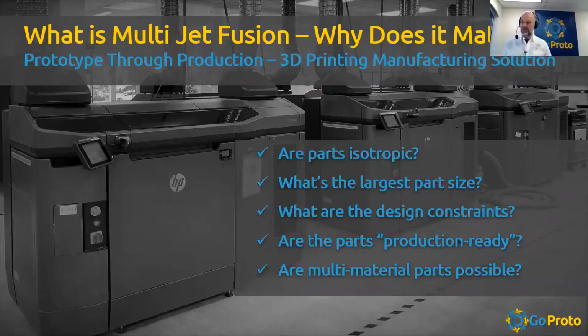What are the design constraints? Again, these are questions, as Kristen mentioned earlier, that some of you had as you registered. So these are directly from the market. Design constraints, that's an exciting thing about 3D printing. Why 3D printing is interesting is because you don't need tooling to make parts. You don't need to do things like draft and consistent wall thickness like you're used to designing for injection molding. Undercuts only become important in that we need to be able to remove the powder. It needs to be something that we can get compressed air or tumbling in to get the powder out.